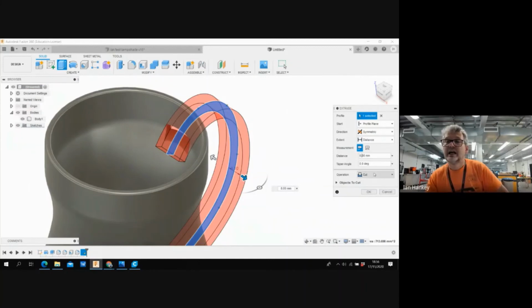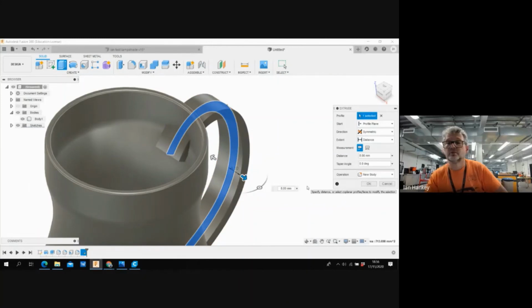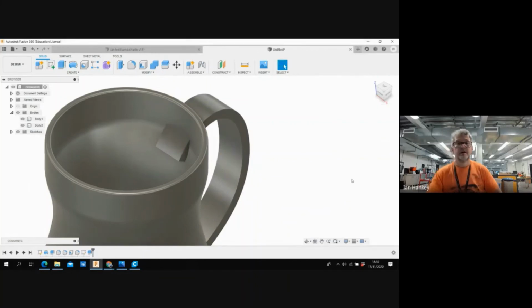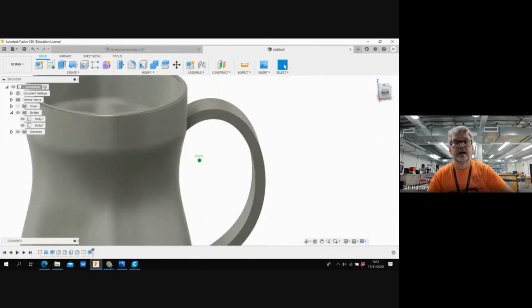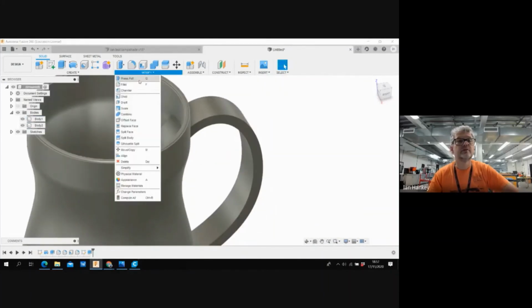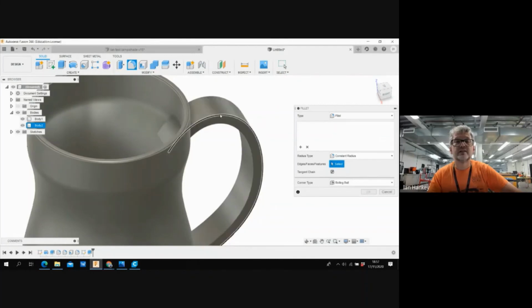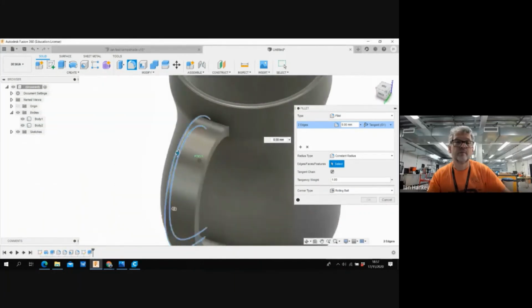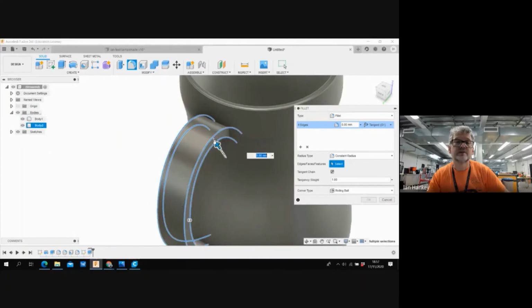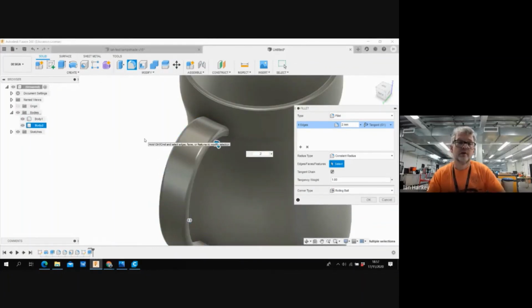That's 8 millimeters. And what I want to do is create a new body. There. So I clicked OK, and we've just essentially made the body from our sketch. Click OK, and there's our body. Now, very, very quickly, because I think we're running out of time, I'm going to put a little bevel on that: modify, fillet. Let's select the top one, that one as well. That's actually wrong. I've just got that, that's it. 2 edges. I'm going to take the top edge there and the bottom edge there, and let's key into all the way around. That's a nice rounded handle there.